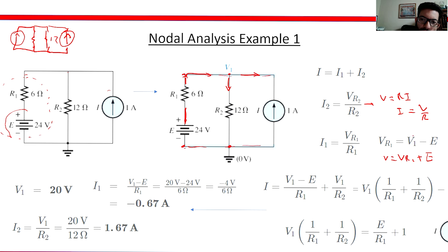Okay, so do we have information to solve for voltage drop 1? Well, not quite. We have this source, but we don't know what V1 is, which is here at the very top. But at least we have an equation that will relate the voltage drop through resistor 1 and the total voltage from the maximum potential and the source.